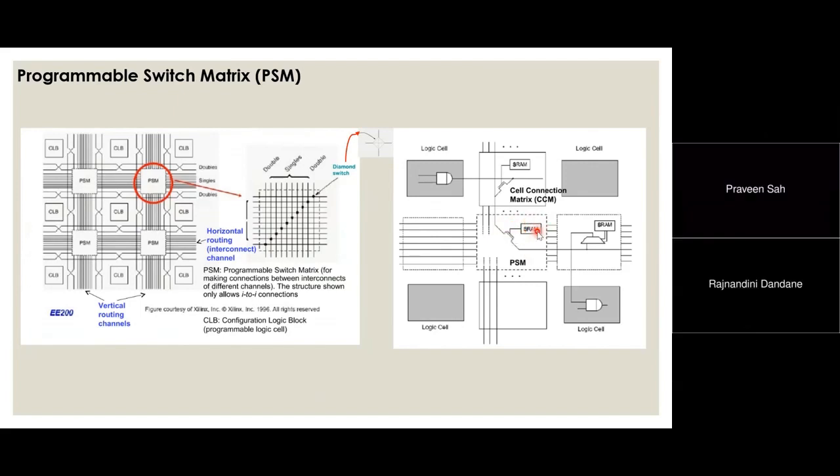With the SRAM. And as I told you, whenever you write the logic, the tool writes the truth table back into the SRAM. It means once you describe what CLBs are connected to this, what you are trying to do is make this SRAM on. So basically the tool will write one over here. If this is an NMOS transistor and you provide a one, it will be on, so whatever input is available will be available at the output.